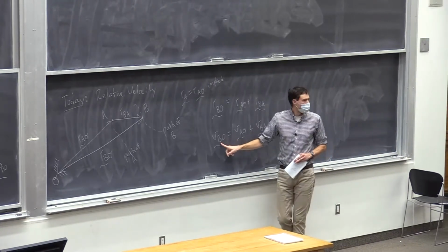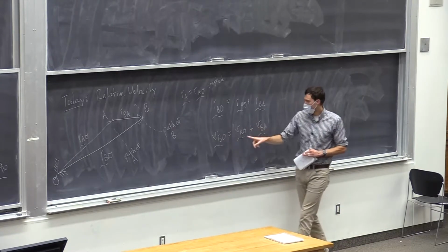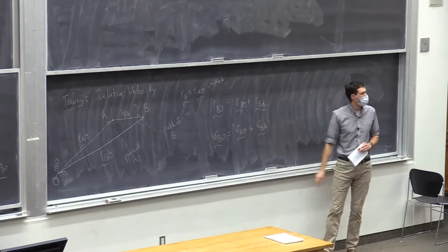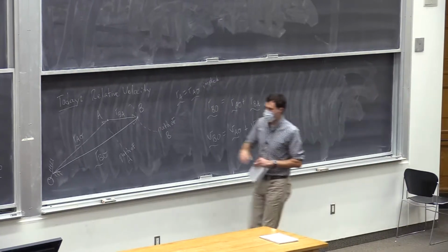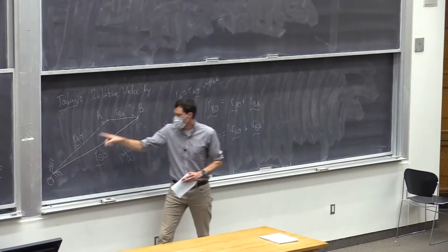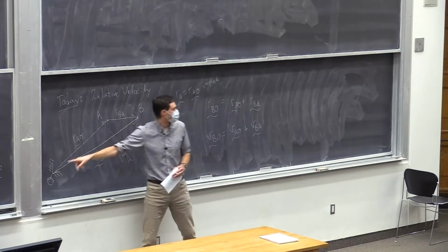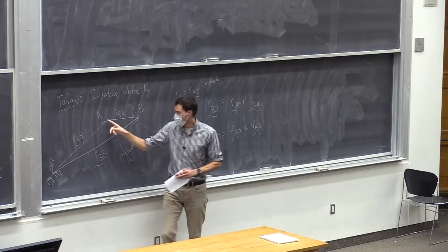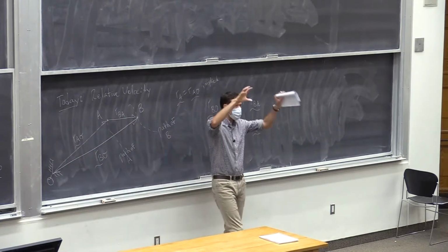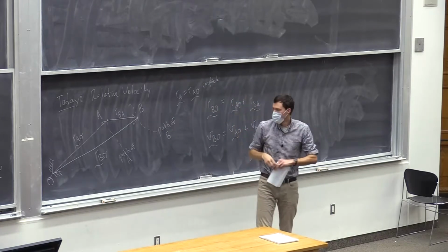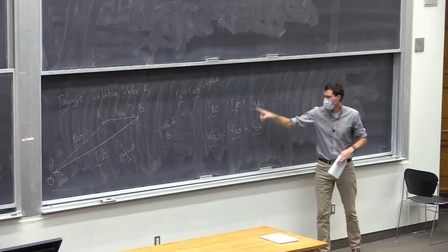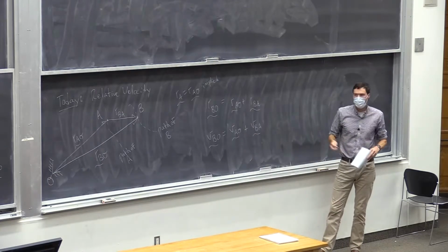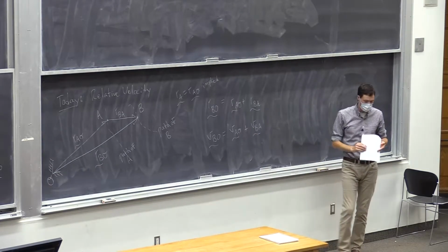If we want to find the velocity of B, we can step through point A. This seems abstract for now, but in a little bit we're going to connect these vectors to links in our mechanism. These points of interest are going to be our turning pairs or sliding pairs through our mechanism, and we're going to draw some vector expressions for positions and velocities graphically, and then write out their equations.